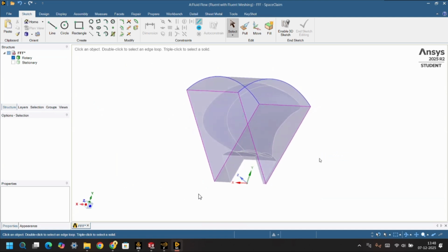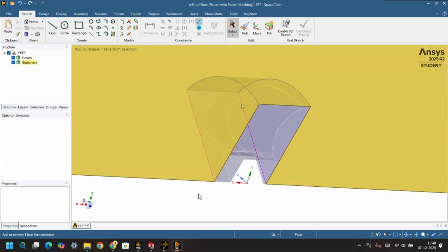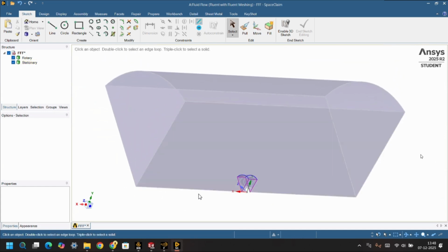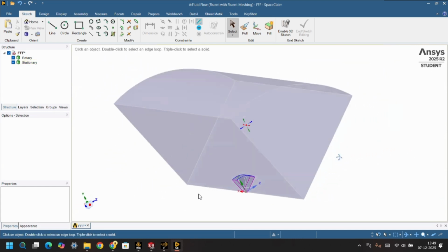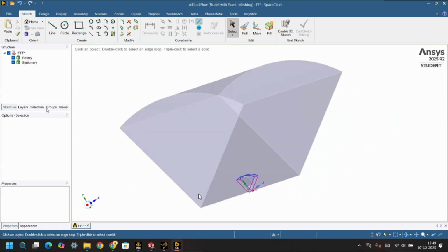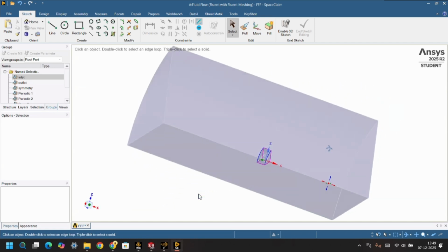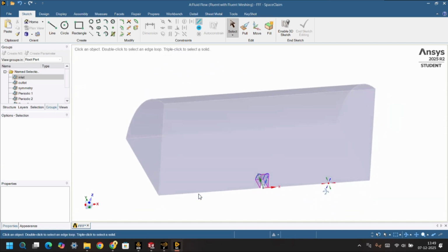Moreover, the stationary domain that we added, aside from the rotary domain, since we are using the multiple reference frame method to simulate the rotation, the stationary enclosure was a very large size, around 4 to 5 times the diameter for the inlet and outlet, and 3 times the diameter for the size of the far field boundary condition, or the outer cylinder wall.